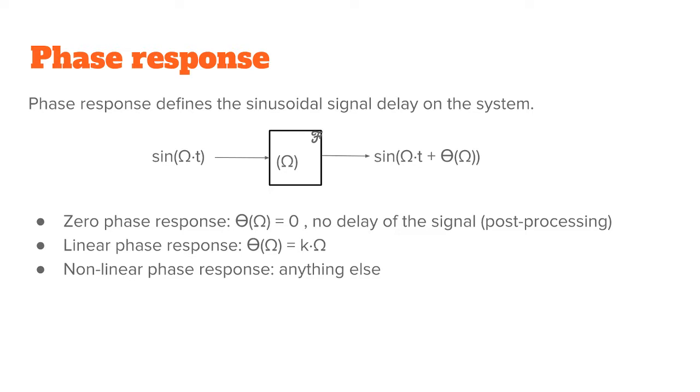Okay, meaning that if you have a really ugly looking signal coming in here, different frequencies on it, the only thing this system does for this signal is, it just filters the amplitude but doesn't really touch the phase. It's just a time delay.